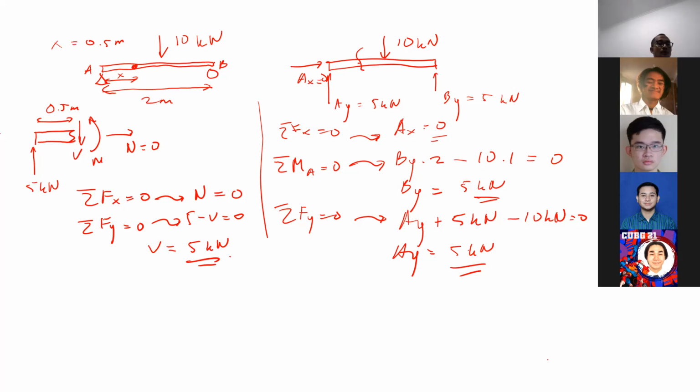Okay. Now let's deal with the sigma moment equal to 0. Where you want to put it, Mario? I mean, the location, the center of rotation. Where do you want to put the center of rotation, Mario, for the sigma moment? At A. At A, okay, correct. You can do it, or you can use the section location as well. You can do that, but you choose A, okay.